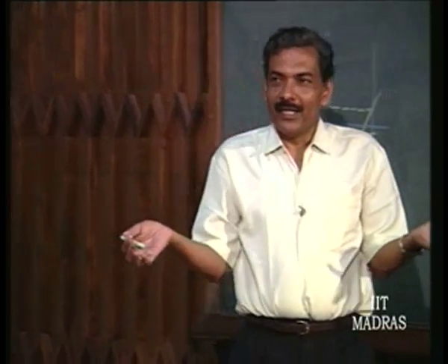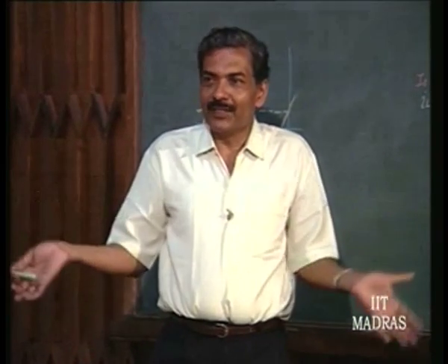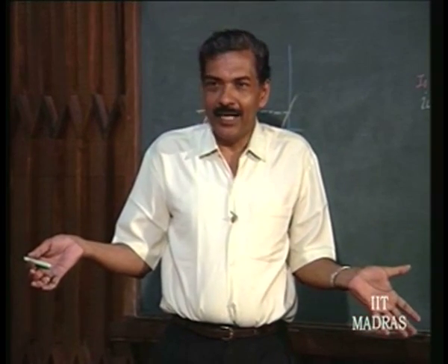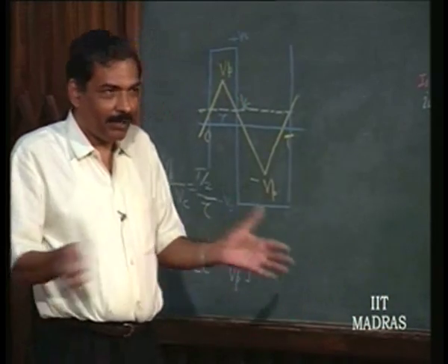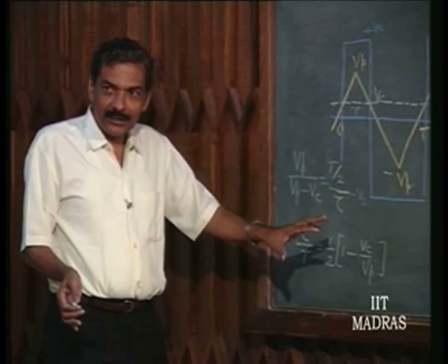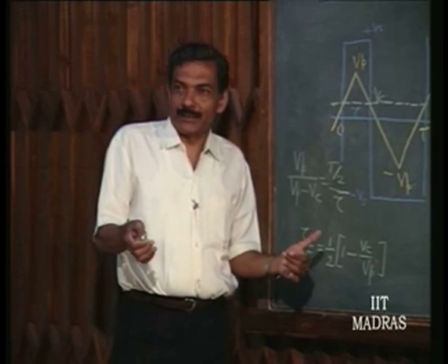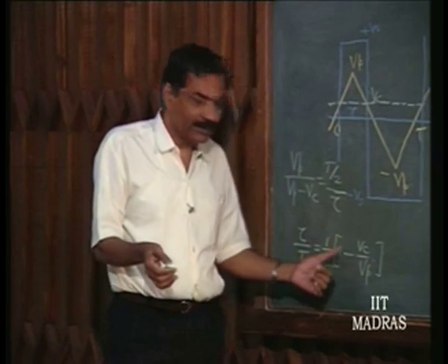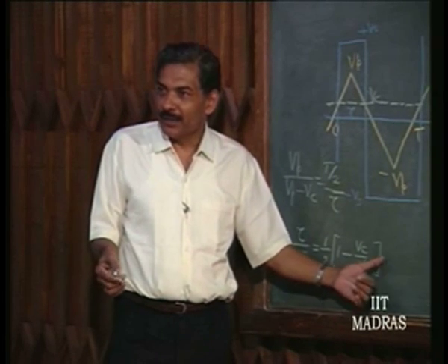Now, if it is connected to the load through a filter, you will get the audio output. That means the efficiency of that power amplifier is going to be theoretically 100%. That power amplifier is called a class D amplifier. In this particular regulator case, it is used for control purposes, that is all. This information is used for control, not for other purposes.